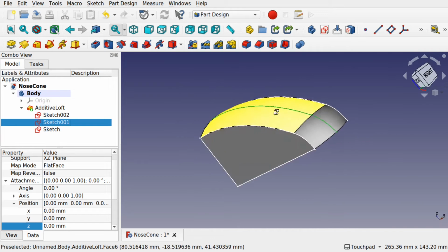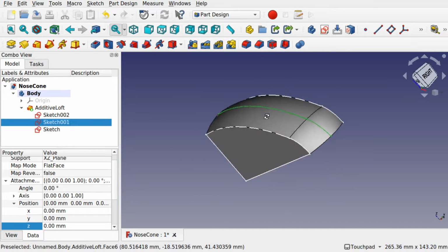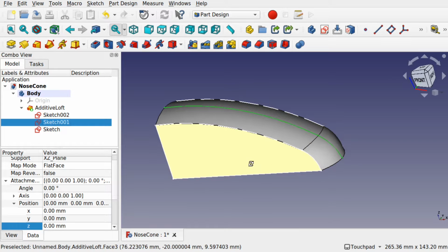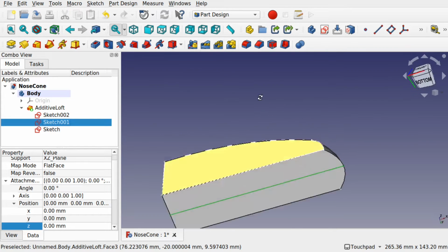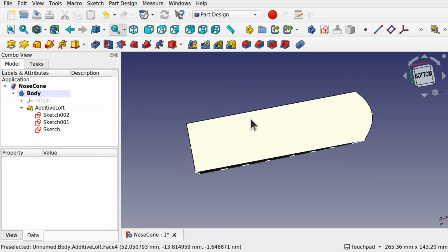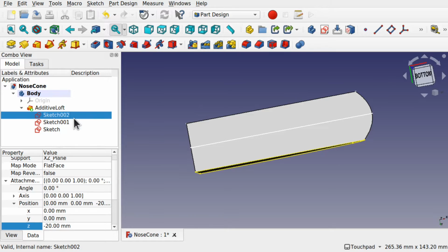So I created a curve across there, so it's nice and curved now. I want to draft these ends towards a point now. So let's come down to the bottom. We're going to use this bottom. But to do that, we need to disassociate these sketches from their support.